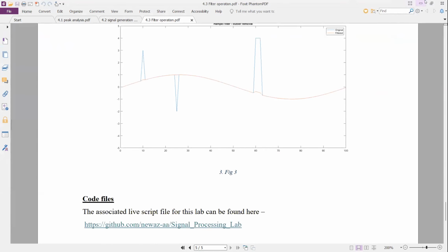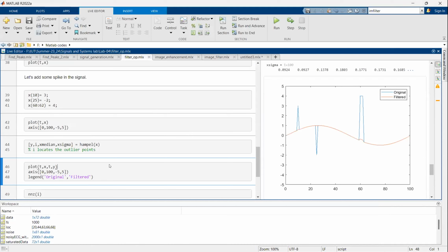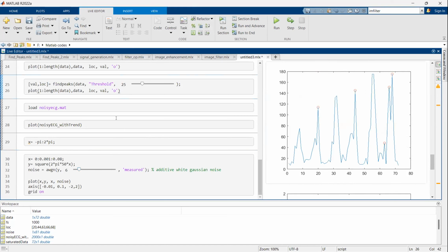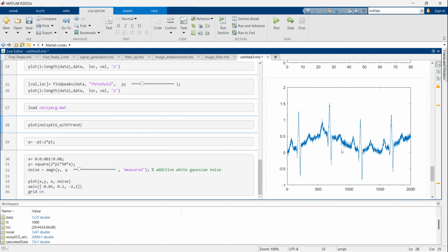So these are two types of filter. There are many filters; these are the two I just introduced. If you have a very noisy signal, you should try the median filter and find the order that makes your noisy signal much closer to the normal signal. And if you have spikes in your signal, like in your previous ECG signal, you should try to pass a median filter there to see if you can make the signal more stable. I'll try to put some assignments of this type in your lab.